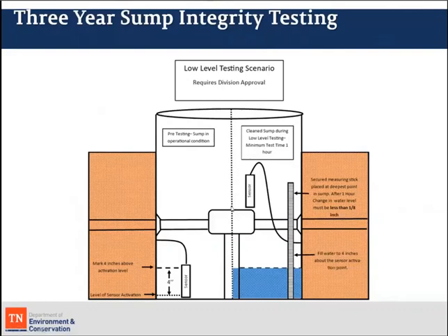Make sure that your Schrader valves are opened or removed, so you have that hydraulic conductivity from your piping to your sump. Because if you don't do that after you perform your test, you really are not performing release detection again, because all these components have to work in unison for this to work.